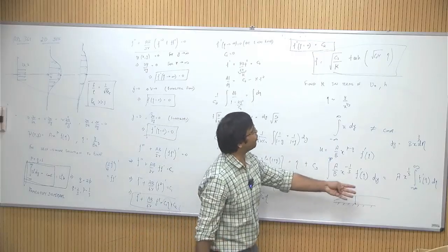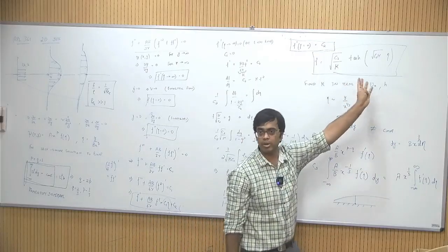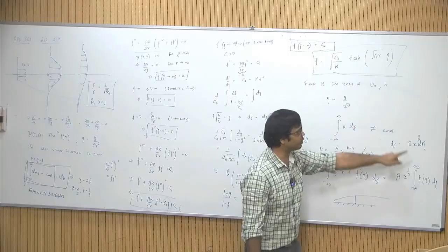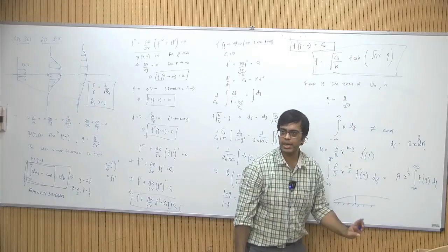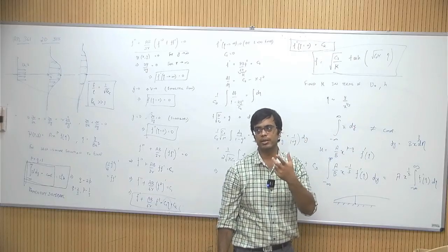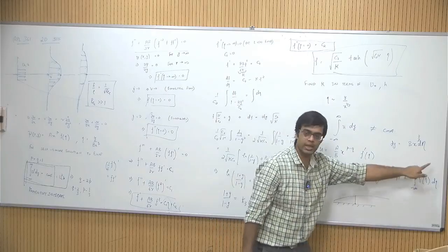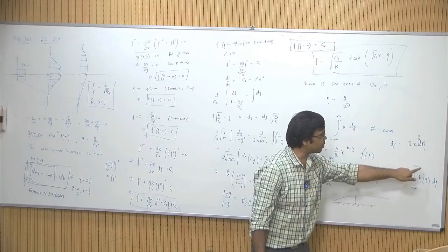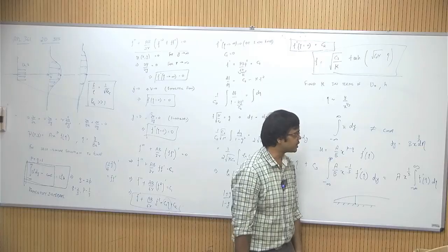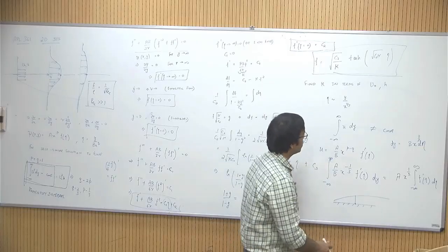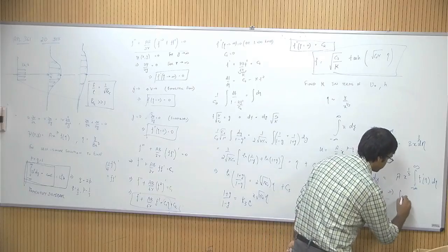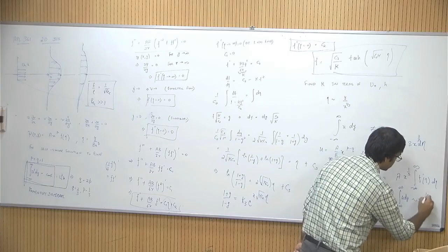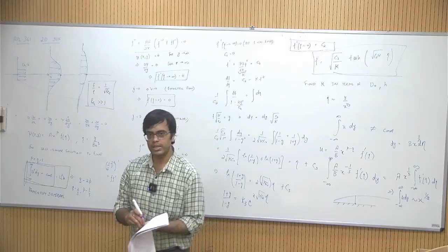So whatever your f prime is, you just differentiate this tan hyperbolic, you will get some secant hyperbolic square or something like that, and you substitute it here, you integrate it. Eventually you will get a constant because this is a definite integral. I mean, this is improper but definite. Okay, you can evaluate those limits. So eventually you will conclude that your mass flux is increasing in x, and it is increasing as x to the power 1 by 3.